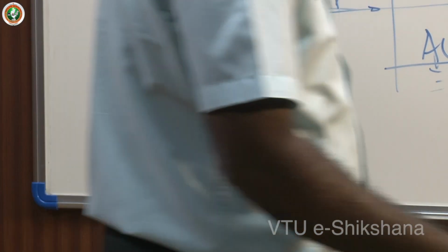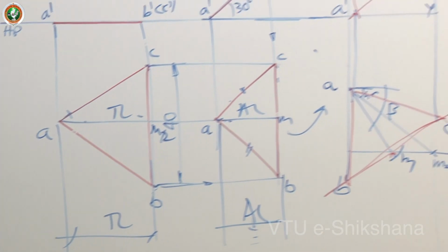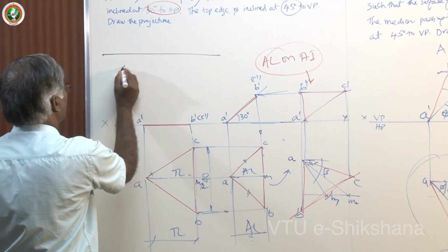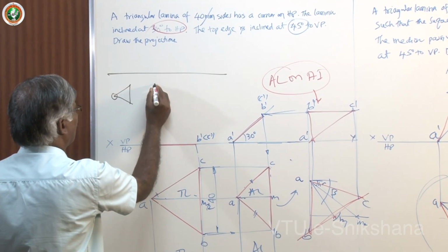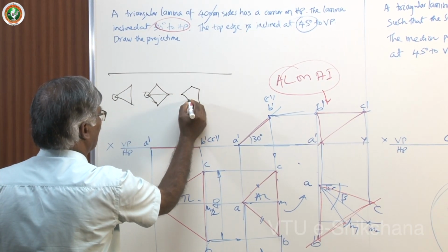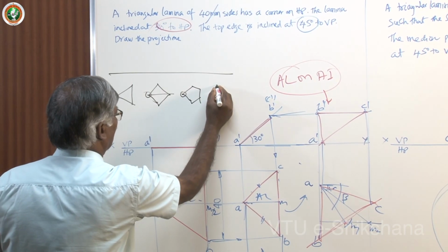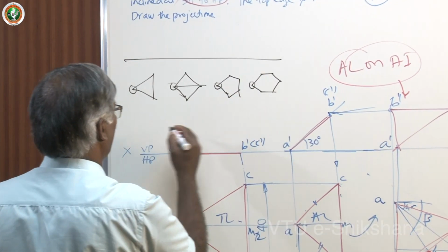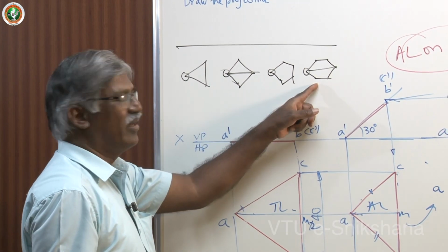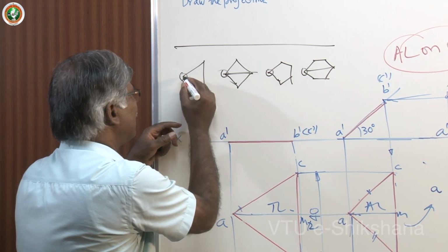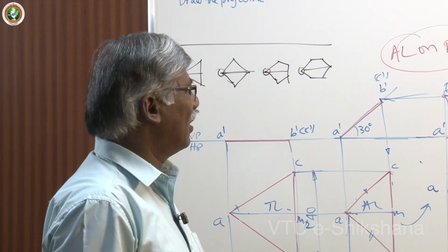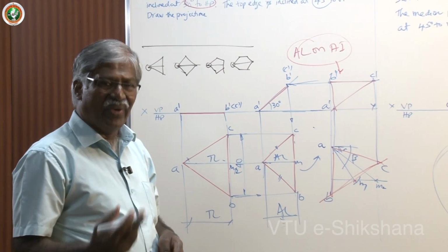Okay, I will draw simple sketches for the corner condition of the standard laminae. This is the corner, square, this is the corner, pentagon, this is the corner, and hexagon, this is the corner. Here you just observe the diagonal for square and hexagon. For pentagon, this is the median, this is the perpendicular bisector. That's all. You can work any problem on corner condition, and also beta if necessary.